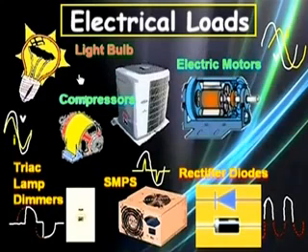A 100-watt incandescent light bulb is a resistive load that only consumes true amps and dissipates watts as heat and light. The AC current and voltage are in phase and there is no power factor. A big industrial motor like this one, with its many inductive windings, causes a phase displacement between the AC current and voltage and creates additional reactive amps needed to expand and collapse its magnetic fields. These reactive amps do not produce useful watts.